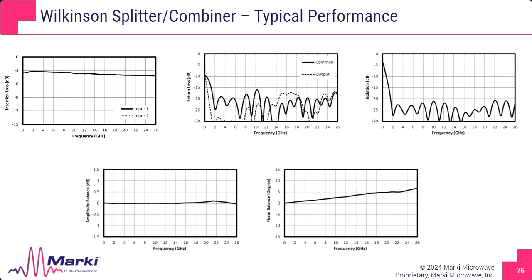You can see there's a spike in return loss, which kind of correlates to this dip in insertion loss, or I'll circle it here. But it's primarily the isolation here that begins to creep up, and we'll see it on this side too. So this is just showing it's the isolation that will limit your bandwidth. You're going to have decent loss. There's a bit of a phase walk off, but you'll maintain the balance out to high frequencies.